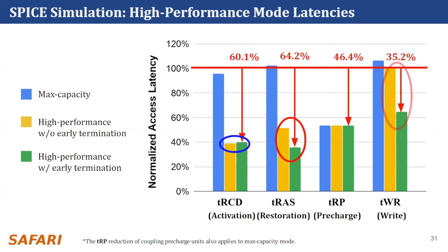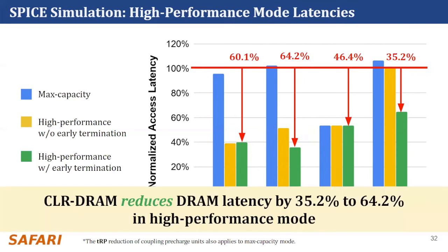Second, the early termination of charge restoration also enables the reduction of the write recovery latency, which is not reduced without such early termination because only one write driver is involved to write to the two coupled cells. We conclude that CLR-DRAM significantly reduces DRAM latency.